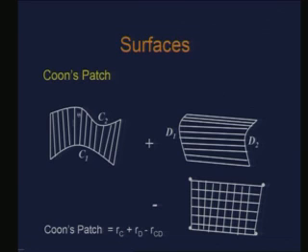Right. So, what I am saying here is that I have the ruled surface which is obtained through C 1 and C 2, let us say I call it R c. This is another ruled surface which is obtained for the boundary curves D 1 and D 2, which is R d, and this is the bilinear surface for the four corner points, which I call R c d.